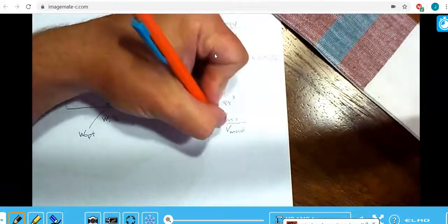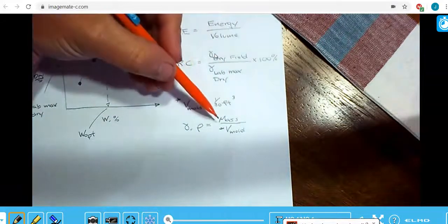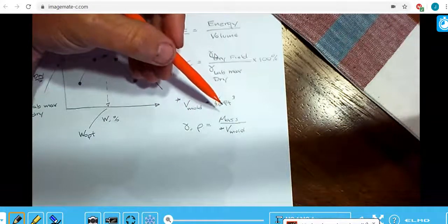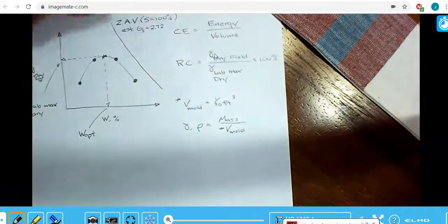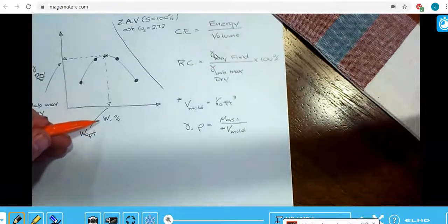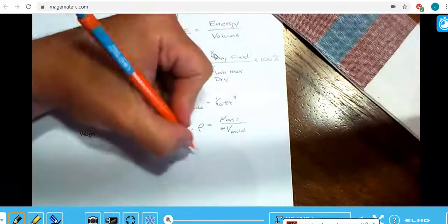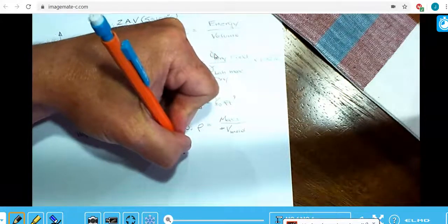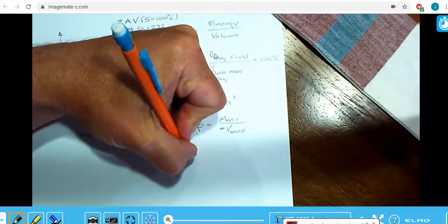And that's known. Okay. And after we compact the material and get the total unit weight, then we extrude all the material, we take it out of the mold, and then we take a portion of it to measure the water content. So we measure what the water content was during compaction, or the molding water content. And then if we have the water content and the total unit weight, or the total density, then we can calculate the dry unit weight, or dry density.